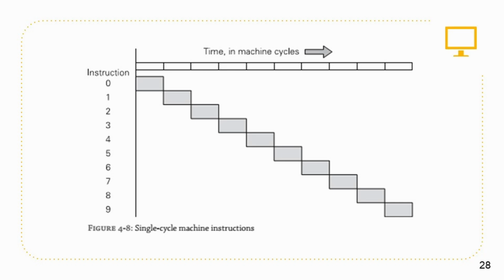5. Pipeline stalls. CPU pipelines can experience stalls or delays due to various factors such as cache misses, branch mispredictions, or data hazards. When a pipeline stall occurs, the CPU may be unable to progress until the issue causing the stall is resolved, resulting in increased latency for affected instructions. Instructions that encounter pipeline stalls may take longer to complete execution compared to instructions that execute smoothly through the pipeline.